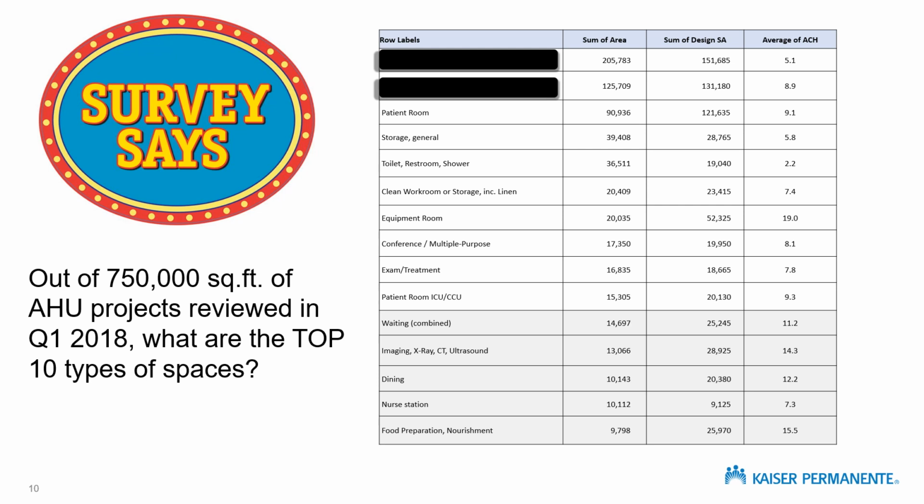On the summertime. In the neutral condition, anywhere else in the country, you can drop that down to 4 air changes. In California, you'll likely be in economizer mode using 100% outside air, and you can drop that down to 2 air changes.